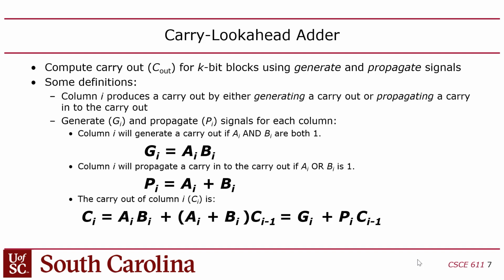You end up with a Boolean expression with a lot of different P's and G's from all the prior columns, right? Now, in principle, you could do that with just 2 levels of logic, a product of sums. But that expression is going to get big because you're going to end up with a lot of inputs to the gates in there, particularly the OR gate at the end. You guys with me? It's not scalable. Basically, the only way you can really do that is on a small group of bits. But you can extend this method and make it hierarchical.